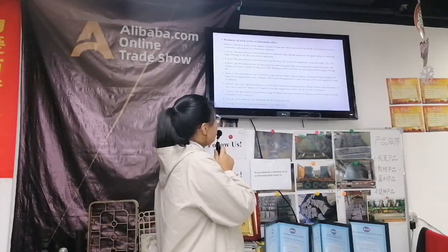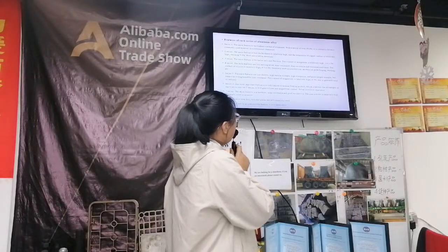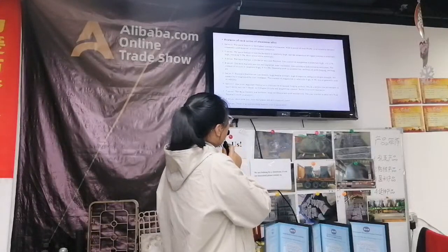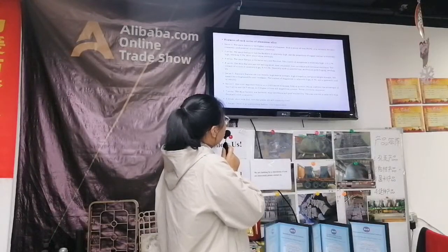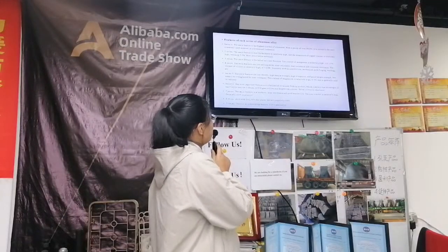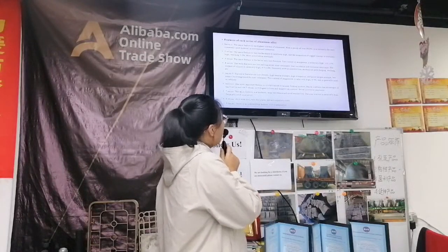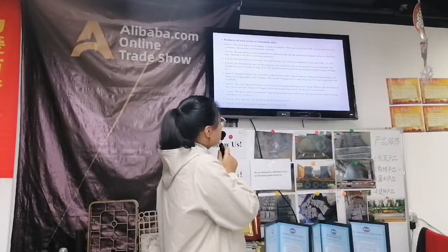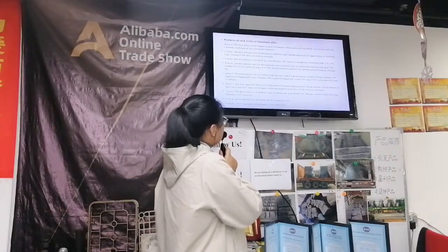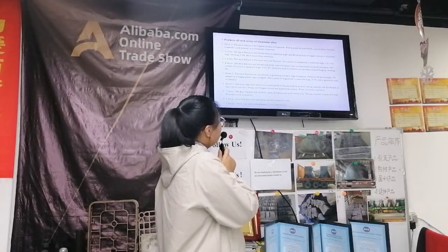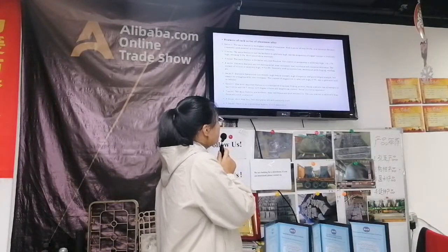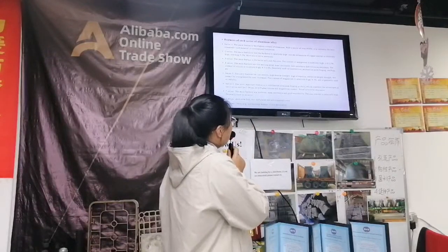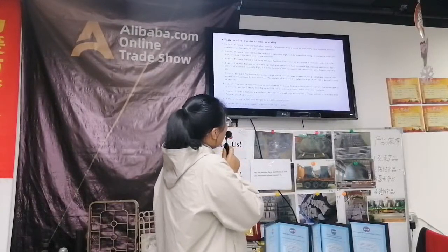3 series: the main feature is better anti-rust function. The content of magnesium is relatively high, 1.0 to 1.5%. 4 series: the main features are low melting point, wear resistance, heat resistance, and corrosion resistance. The content of silicon is relatively high, 4.5 to 6.0%. Generally used in conduction, mechanical parts, forging, welding.